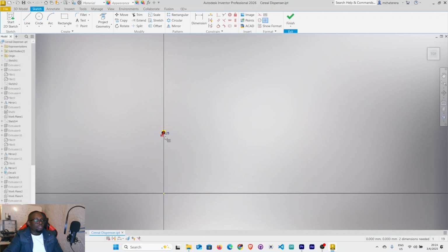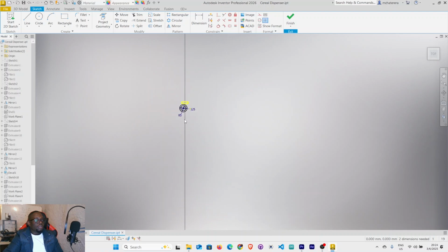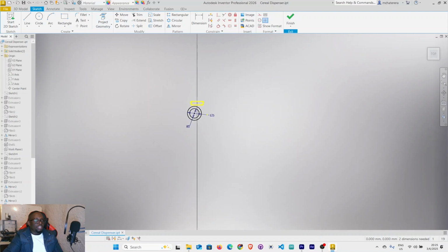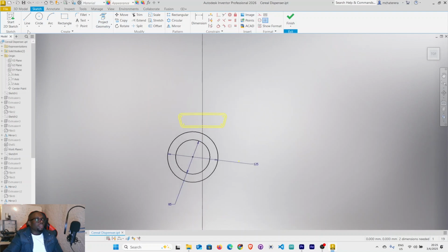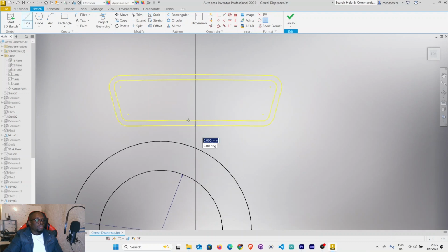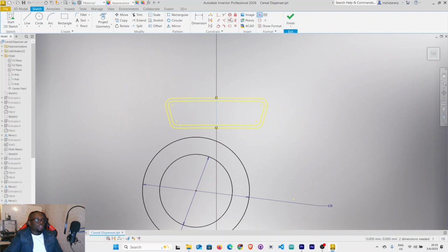Let's see, do you have an axis? I want to project, let's collapse this. That's not the z-axis. Okay, right click OK. Let me just draw a line of symmetry here. Select the line 2. Right click OK. Let's make this line a construction line, and let's use the vertical constraint.